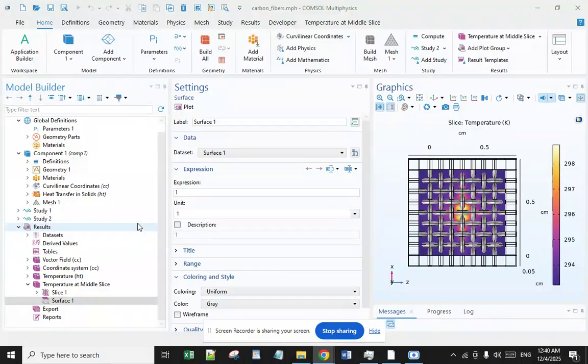Mainstream composite manufacturing techniques include autoclave processing, resin transfer molding or RTM, vacuum assisted resin infusion or VARI, automated fiber placement or AFP, thermoforming, and pultrusion. Controlled heating is used in all techniques in combination with pressure or vacuum to reduce the matrix viscosity to facilitate resin flow, impregnation, or bleeding and layer consolidation, as well as to affect solidification via curing for reacting resins, especially thermosets, or cooling